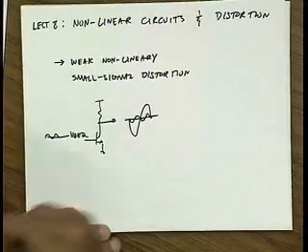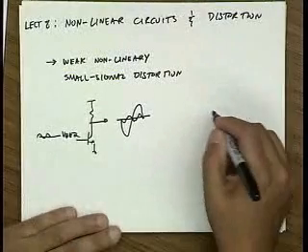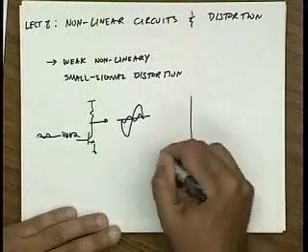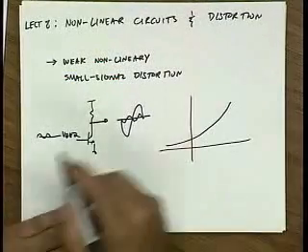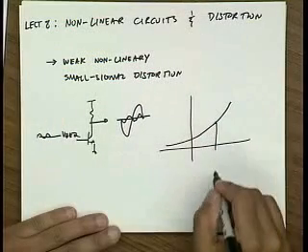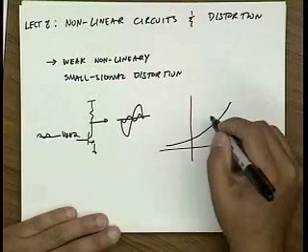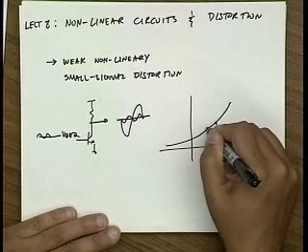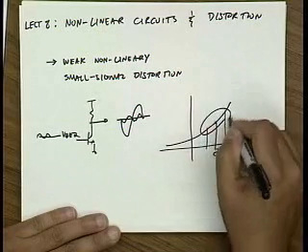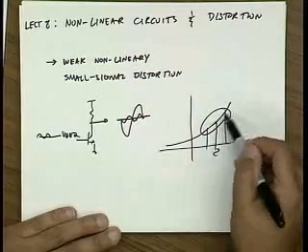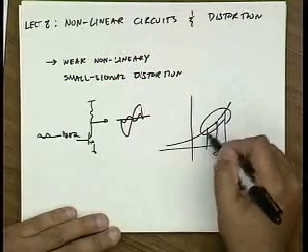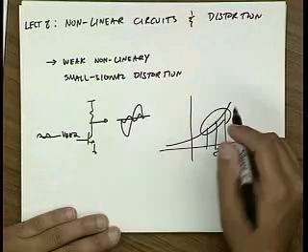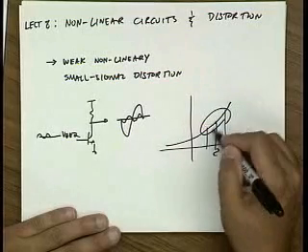Now if we look at a typical nonlinear curve for a device, and we consider applying a small signal, then doing a Taylor series expansion around this point in this region is going to be quite accurate. Even just a simple third order polynomial will describe pretty accurately the shape of this curve.